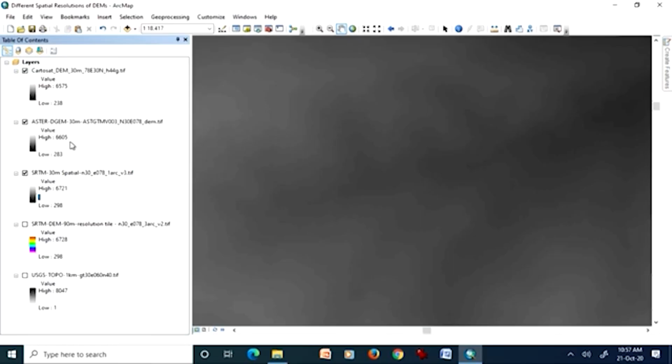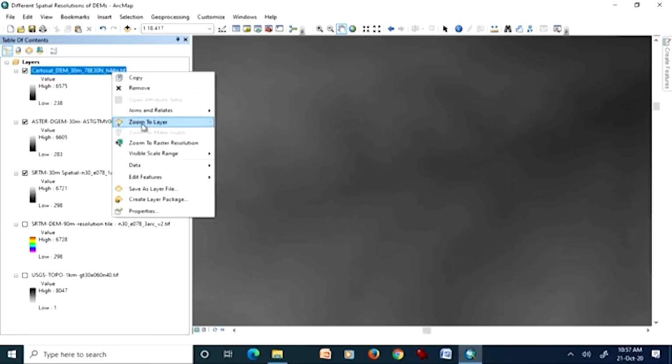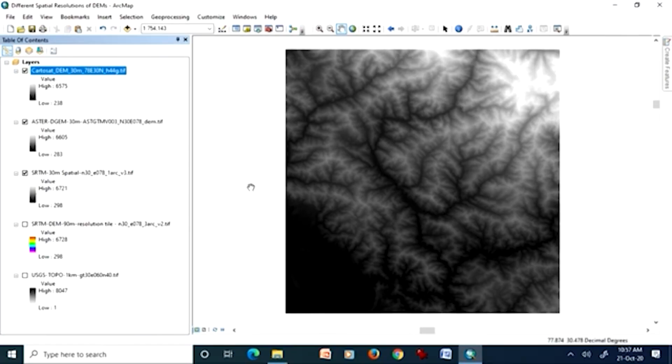You can generate random points for the same extent, maybe 100 or 200 points, and then enrich the attribute table of those random points through all three digital elevation models. So in your random point attribute table, you would have a height field from SRTM, an elevation field of ASTER GDEM, and a third field for Cartosat DEM.